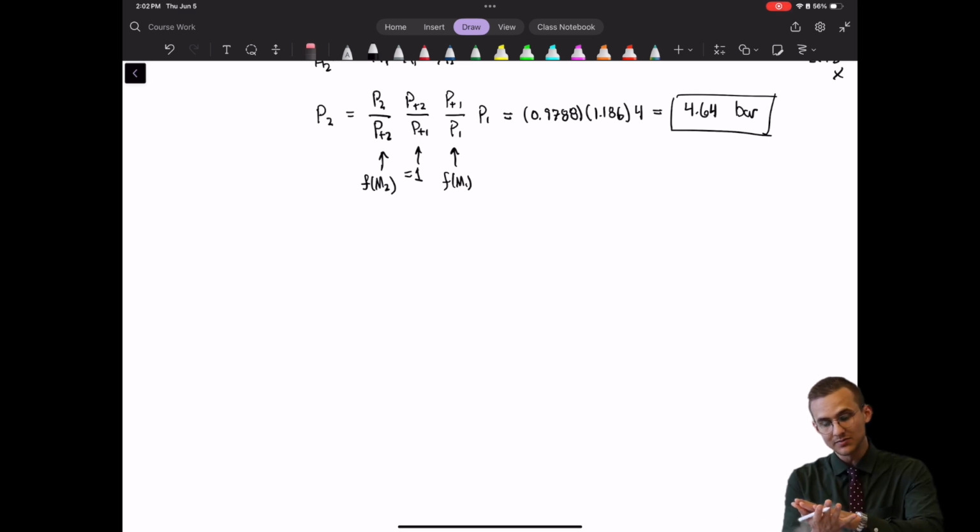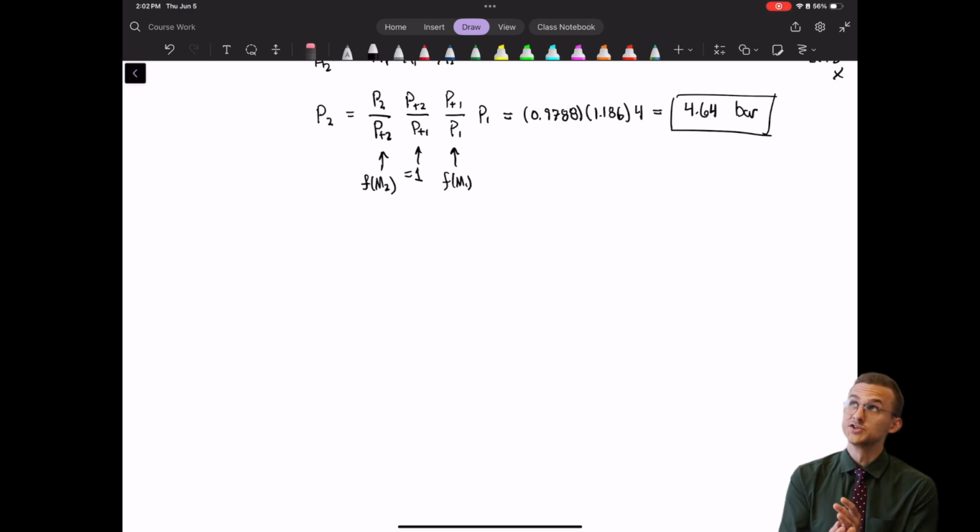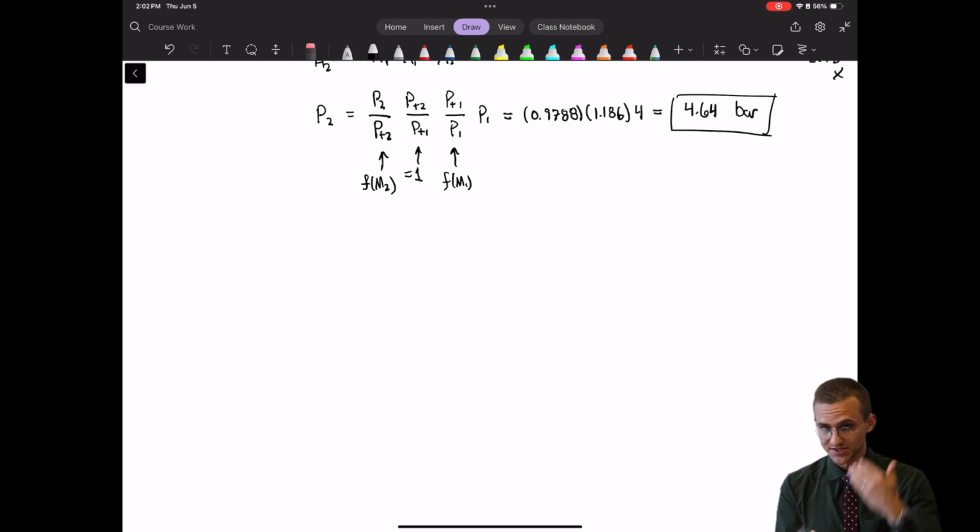If you're given a Mach number, that gives you all the isentropic relations, the ratios between static values and stagnation and sonic values at specific points. And you can also hunt down a Mach number by knowing the ratios between static values and reference state values at those points.